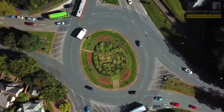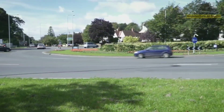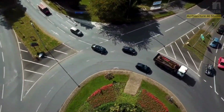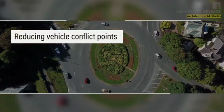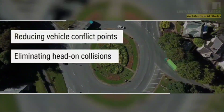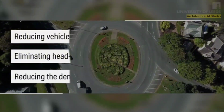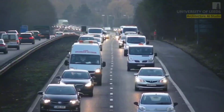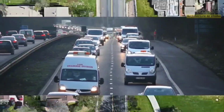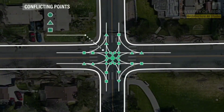Compared to a priority junction, that is, a junction without traffic control, the roundabout has a number of benefits in capacity and safety enhancement. These include reducing vehicle conflict points, eliminating head-on collisions, and reducing the demand for traffic control. Conflict in the direction of flow often results in the slow movement of traffic, also known as congestion. Therefore, the overall capacity for a road depends significantly on the performance of its intersections.